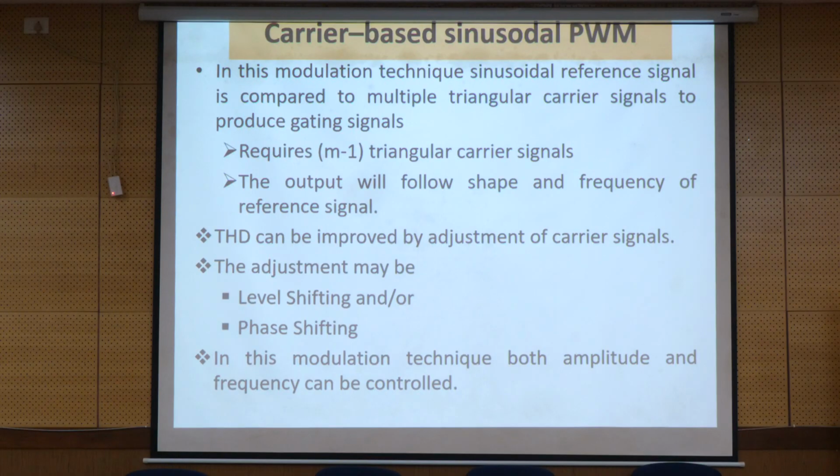For multi-level inverters, the carrier waveform is of high switching frequency and the reference waveform is equal to your fundamental voltage level, that is 50 hertz, compared with the 1000 hertz carrier frequency. The switching pattern will be generated and given to your inverter modules.